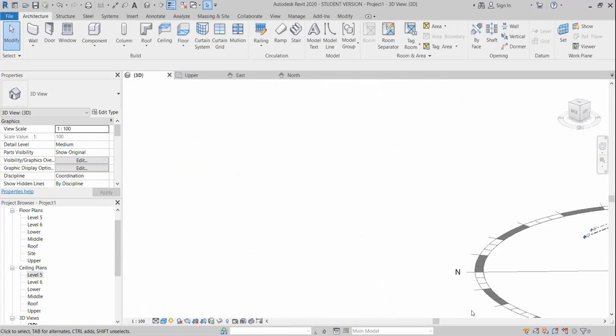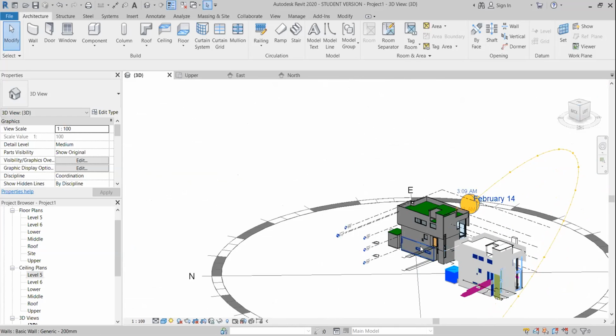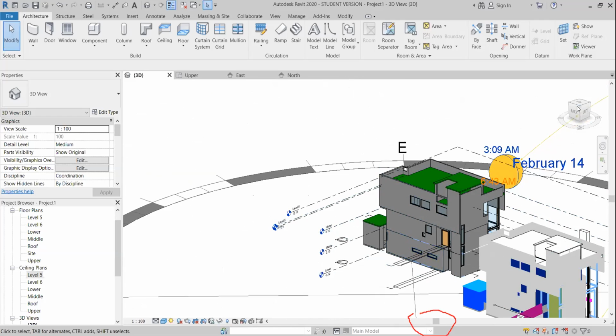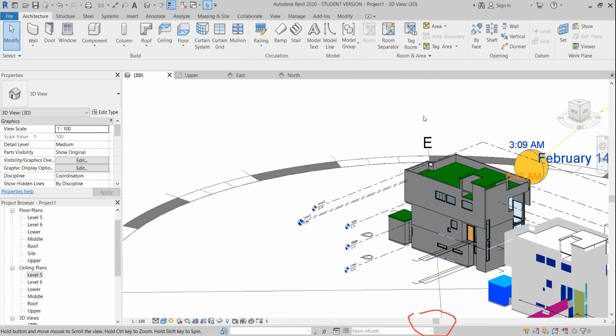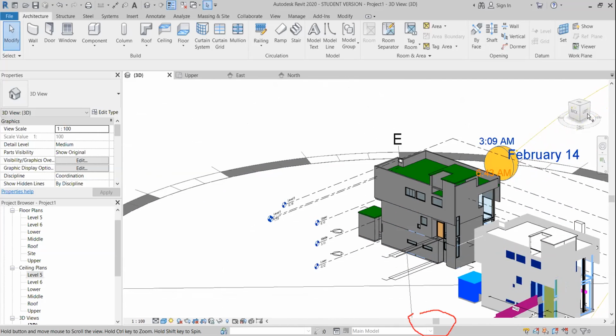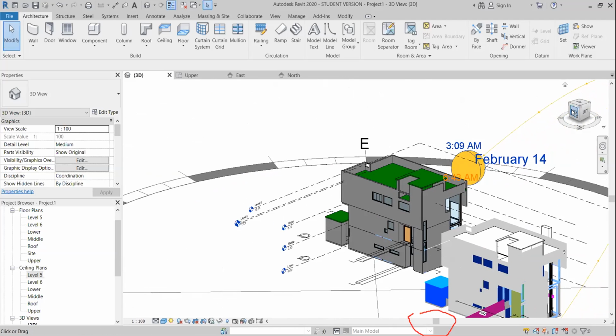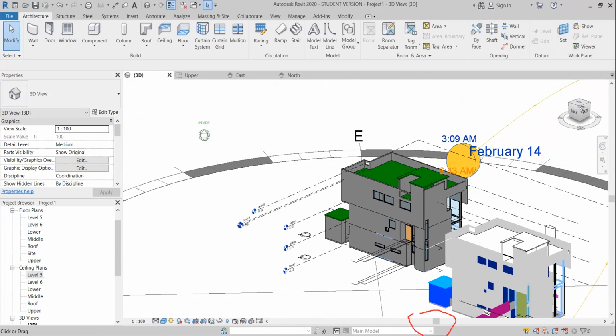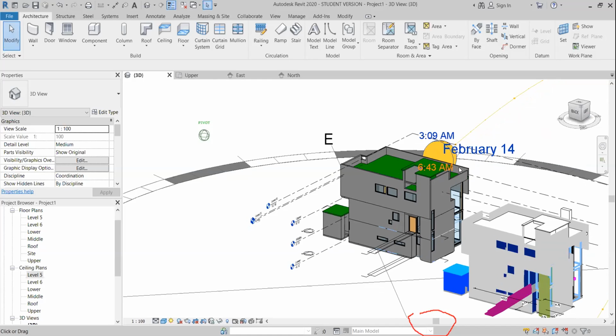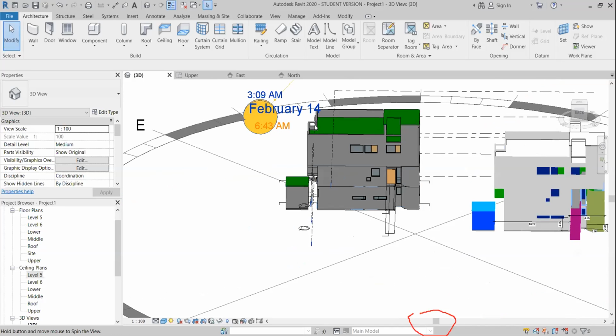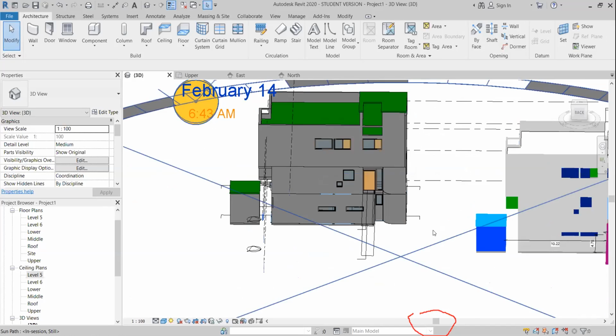You have to select something. And in order to pan, you can press the middle. No need to use this one to pan. You can press the middle of the mouse and drag. See? Yes. So now to orbit, the same thing, please use shift and the middle of the mouse to orbit. And always select something to orbit around. You didn't select anything.